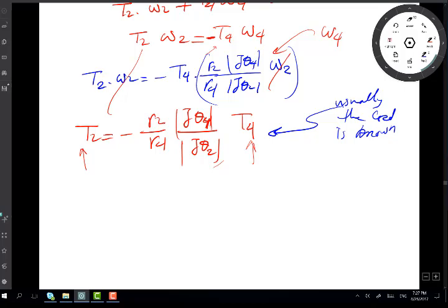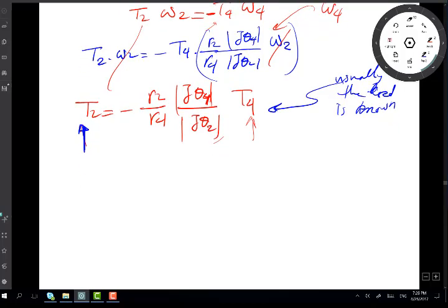So I do these calculations because we don't know exactly how powerful the motor required to drive the thing will have to be. In this case, this analysis will help us make this decision. So in any case, when I look at those together, I want as small as possible T2 to drive the linkage. Don't forget that. So I want high mechanical advantage.